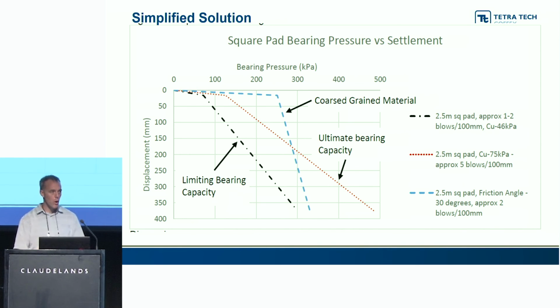And as you'll notice, as you go from small foundations to bigger foundations, bearing capacity becomes less of an issue and settlement becomes much more critical. Once you're over anything of about 2 metres in terms of dimensions, bearing capacity is almost a moot point, and it's almost near impossible to get a bearing failure, but settlement is going to be a significant issue. The key thing to see is this dotted line here is really what our settlement bearing capacity might be